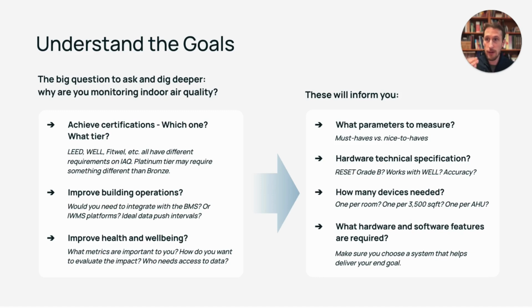If it is supporting an integration to the BMS, is that through BACnet? Is it through Modbus? Is it BACnet IP, BACnet MSTP? Does it go through the cloud? Hint, building engineers do not like BMS integrations that go through the cloud. They like everything to be local. So there's a lot of important points in there that it makes sense to connect with your building engineering team on to make sure that you narrow down the selection that they can actually work with and not bring them something that's going to cause headaches and just lead to roadblocks when you try to roll it out internally.